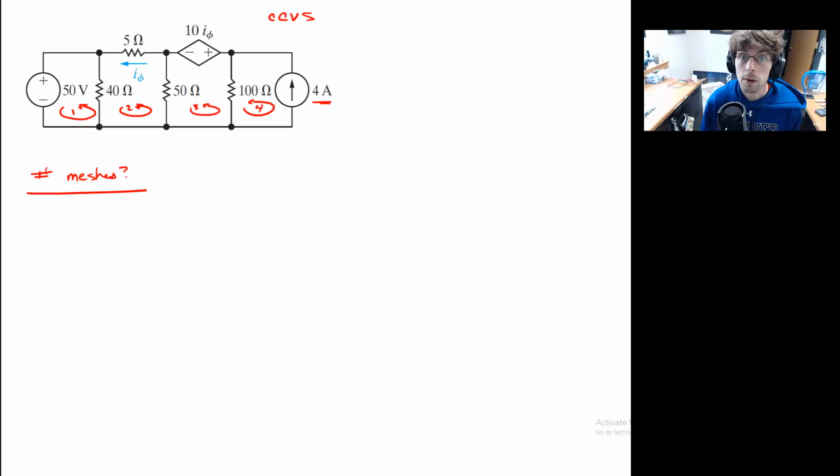We now apply Kirchhoff's voltage law coupled with Ohm's law and write down equations for our 4 meshes. Starting with the top, I know you probably already have this down, but we'll go through anyway. If I walk around counterclockwise, the first thing I have is a drop across this 40 ohm resistor, so I do negative 40 times I1 minus I2. Keep walking around, and I have another drop across my potential supply. And then I'm back at my starting point.